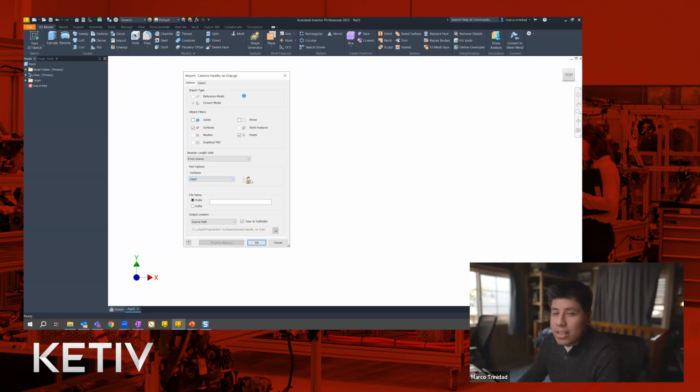Stitch is actually going to stitch the surfaces into a solid. This is only available if you have a fully enclosed surface model. And then construction is similar. It puts them inside of a separate folder where each group of surfaces is its own composite. So I'm going to go ahead and select individual so I can show you a few different tips inside of here.